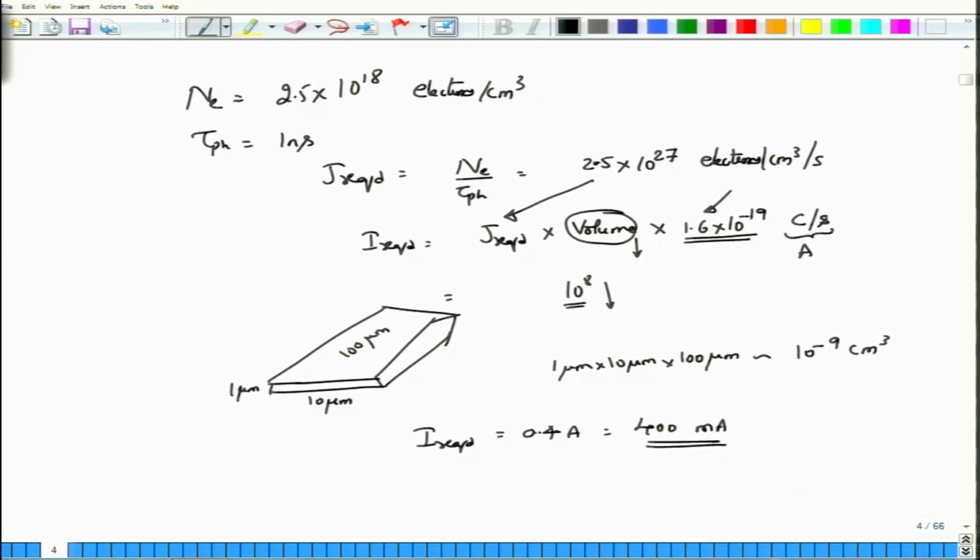Most laser driver circuits will offer 400 milliampere without any problem. Some laser drivers also offer 1 ampere of current if you wish, and those are really the high power lasers. For most communication laser purposes, in fact this 400 milliamperes is according to an older technology.